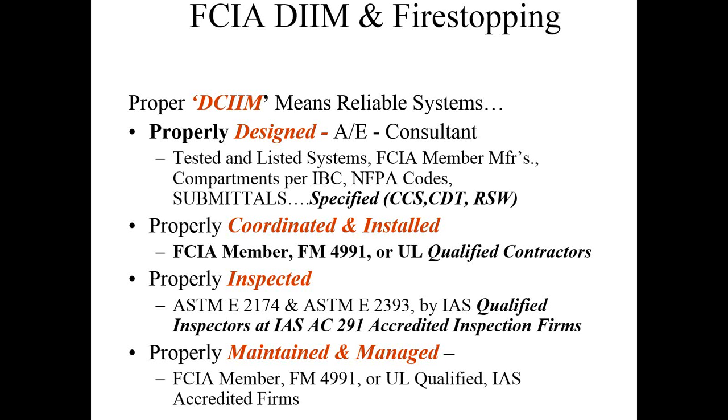Test and listed systems installed by an FCIA member FM or UL contractor, inspected by qualified inspectors, the ASTM E2174 and E2393 standards. Hopefully they're IAS AC 291 accredited. And then maintained and managed by the building owner using FCIA member FM companies, UL qualified companies, and accredited firms.